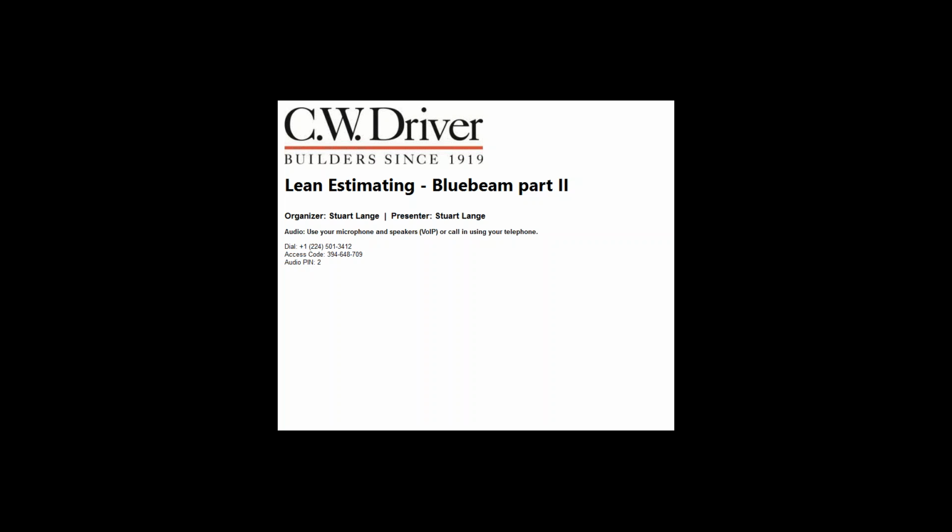Today, I apologize, it's a little small, but we're going to review the document processing and batch linking that we did a couple weeks ago. I'm just going to run through that again, hopefully it's fresh and you're able to do it. We'll see if you guys are practicing. Then we're going to go over takeoffs in Bluebeam and using the tool chest, which, if you think of On-Screen Takeoff, is like the conditions window on the left, where all your takeoffs are stored.